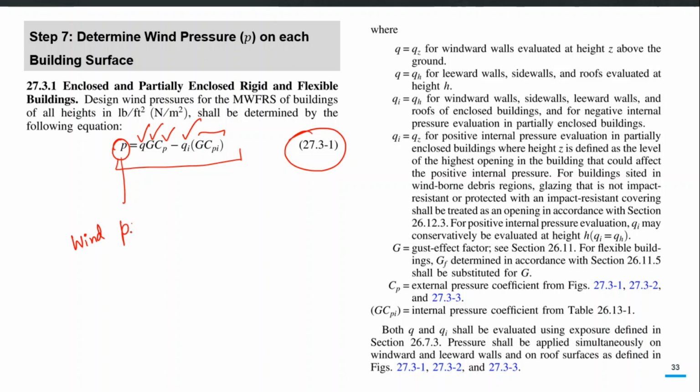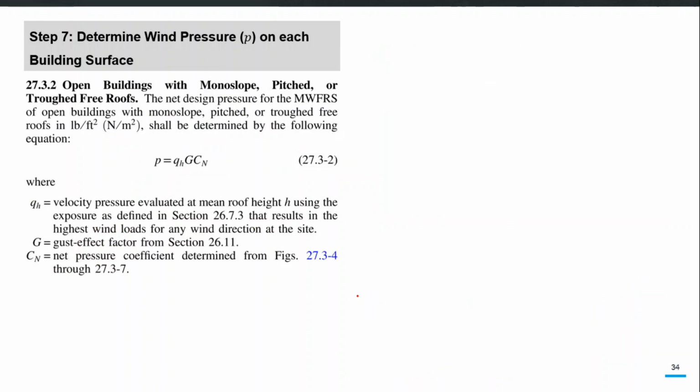Now this wind pressure will be applied to each of the surfaces which is contributing to the exposure of the building and is converted into the wind force and applied at the appropriate locations of the building depending upon whether you use the rigid diaphragm or flexible diaphragm. So I'll explain that in the software demonstration part. So all of the notations which are used in this expression are already explained in previous slides. We can repeat it here, so you can check that one afterwards also.